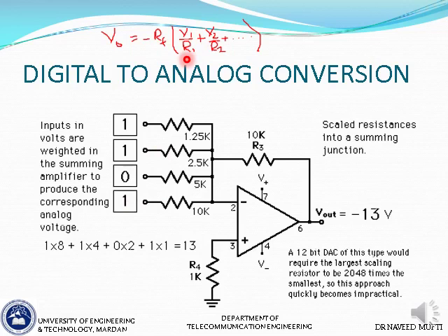So you can simplify, and the answer here is 1. Similarly, if you calculate the second voltage, that is 0. So whatever the value of resistance is, it doesn't matter because the voltage is 0. Now the third voltage is 1, whereas its resistance is 2.5. So it's basically 1 divided by 2.5 here, and there we have got RF, which is 10 kilo ohm.